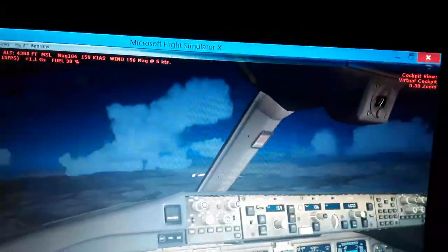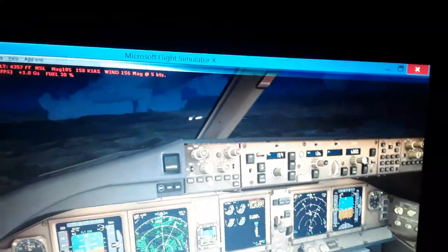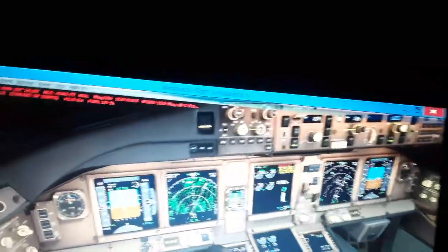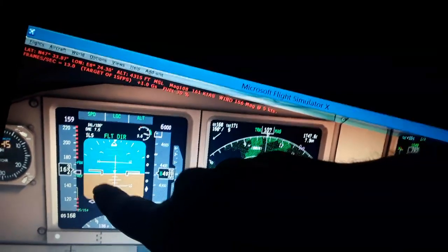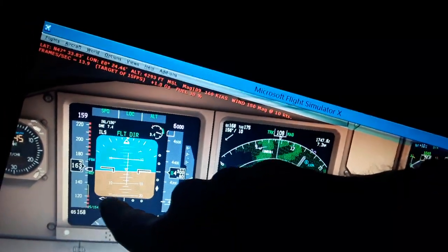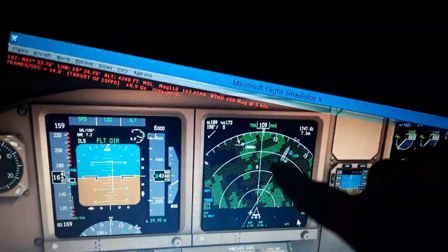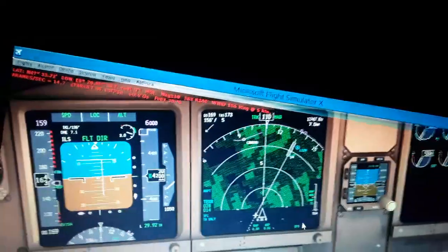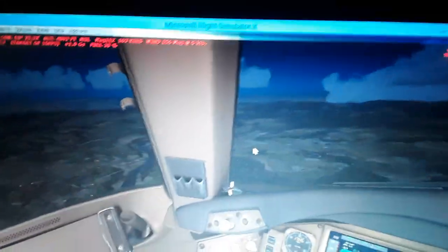And on the landing lights, we need to align. You can see the runway in front of us over here. So we have the LSZH localizer again. You can see the airspeed here. We use automatic airspeed, so we need to turn a little bit to the left, just to align with this line here with the runway, and descend a little bit further. You can see where we are now, our position.